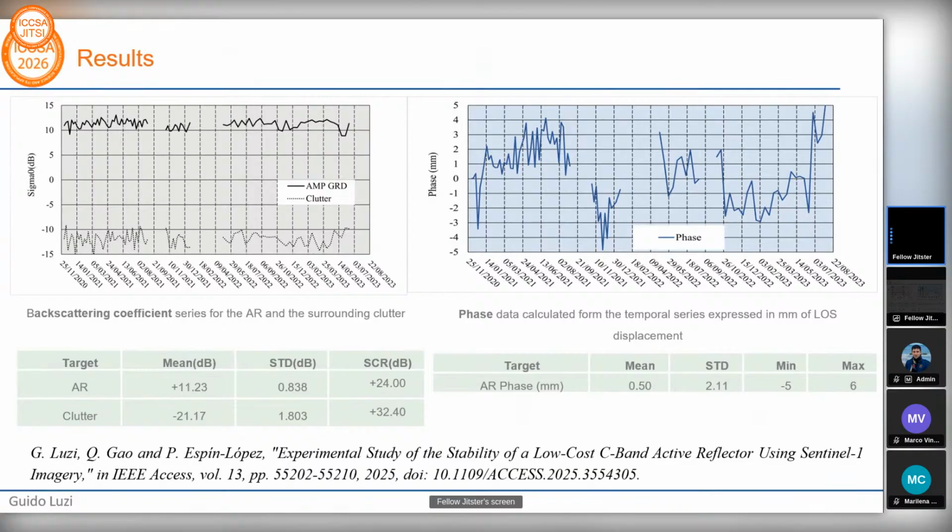And the data are, from our point of view, very good, because the amplitude maintains a set of values which correspond to a stability of the deformation good enough for us. Of course, we are not talking about a geodetic computation where you need an accuracy of a millimeter or less. But if you consider that we are talking about a tool for landslides, millimeter sensitivity and a few millimeters of accuracy is enough for a hydrological study or just for monitoring the situation.